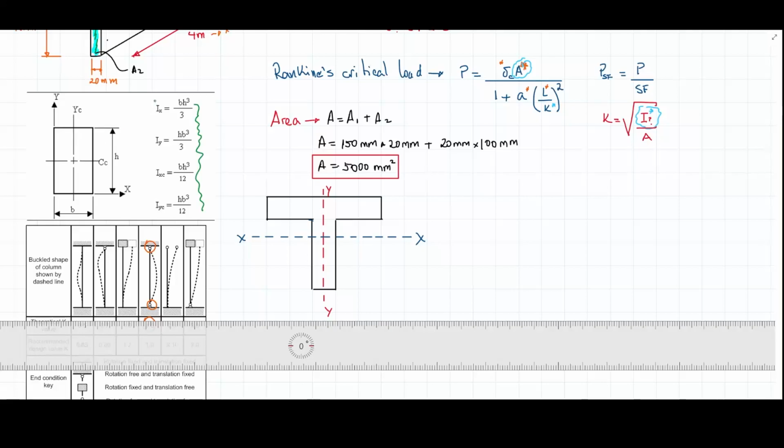And for example, when you find these first two definitions of moment of inertia, for rotation about the x-axis or the y-axis, it says, I'm giving you the inertia of this section, but considering this reference system. So meaning this one here, from this axis. But if I want the moment of inertia looking from the centroidal axes, vertical and horizontal, of the section, meaning this one and this one, you're going to find out that the value changes because they are being looked at from different reference systems.